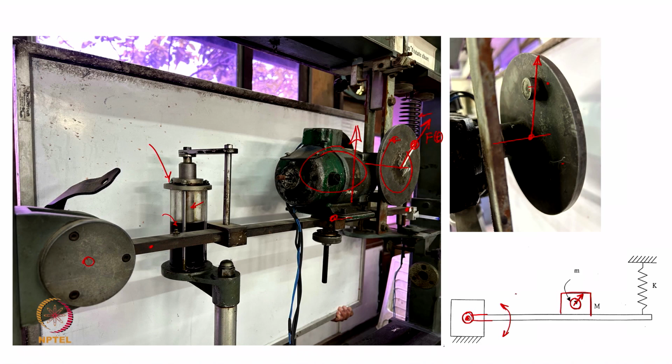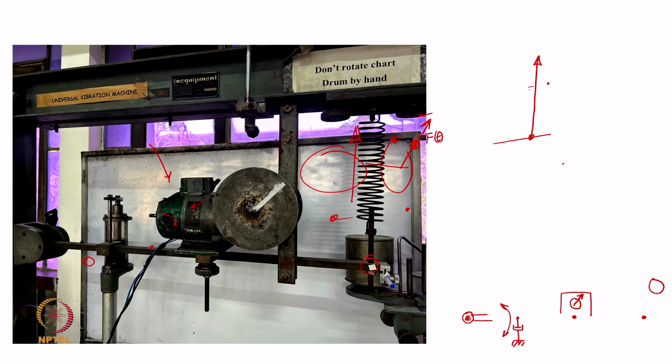Okay. There is of course a dashpot here, which is attached here; schematically I can show it like that. Then the mass sitting here, and the restoring force created by the spring which is at the tip. So, this is the end of the beam where the spring is connected. So, you have this kind of spring-mass-dashpot system comprising this particular vibratory system.